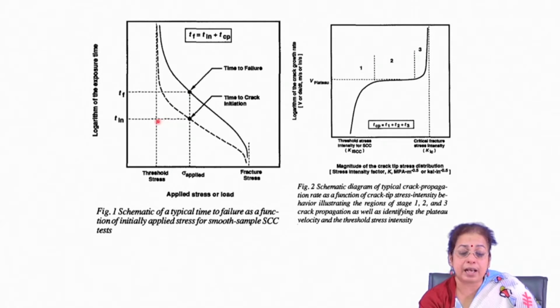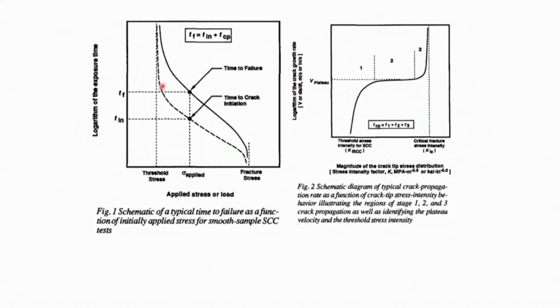On the other hand, as you increase the stress above the threshold stress, you will find that there is a time of crack initiation and a time of crack failure. Basically, at a particular stress there is crack initiation, and at a stress much higher than that of crack initiation, there is crack propagation. This range, the time range between crack initiation and crack propagation, decreases as you go on increasing the applied stress on the surface.